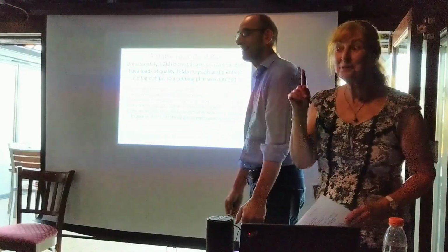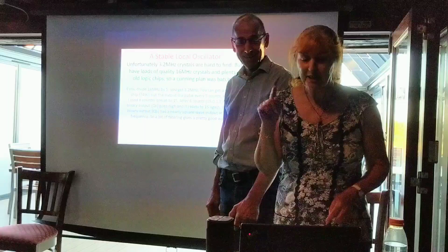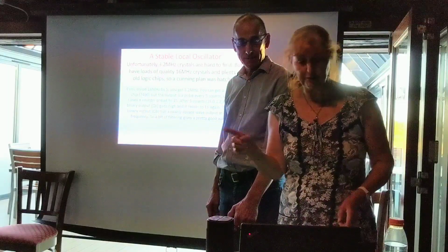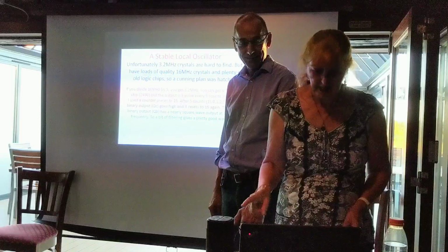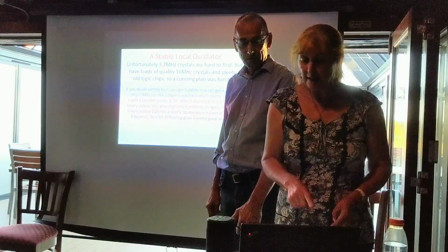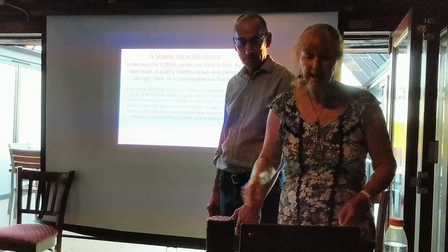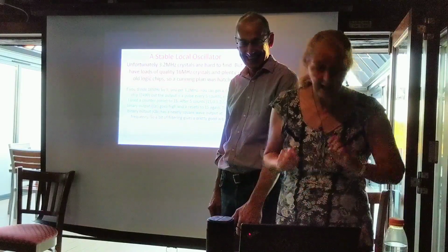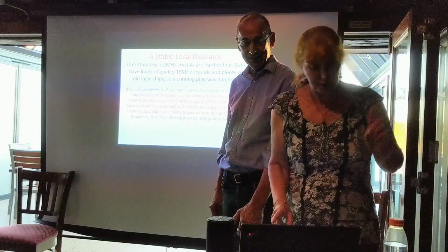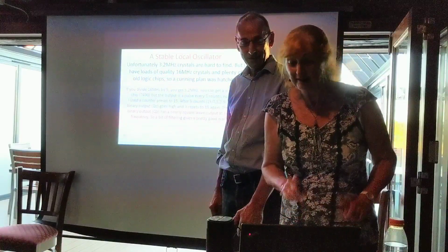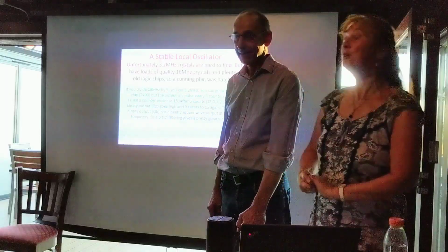So, if you divide 16 megs by 5, you get 3.2 megs. You can get a divide by 5 chip, 7490, but the output is a pulse every 5 counts, no good. So then use a counter preset to 15. After 5 counts, 15, 0, 1, 2, 3, the third binary output, QC, goes high and it resets to 15 again. The second binary output, QB, has a nearly square wave output at a fifth of the frequency. So a bit of filtering gives a pretty good waveform.